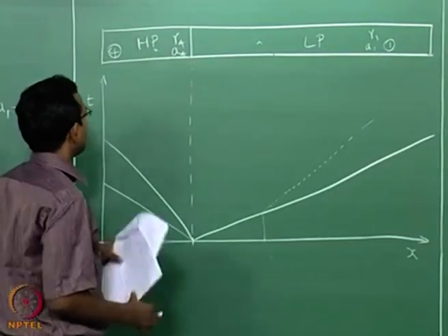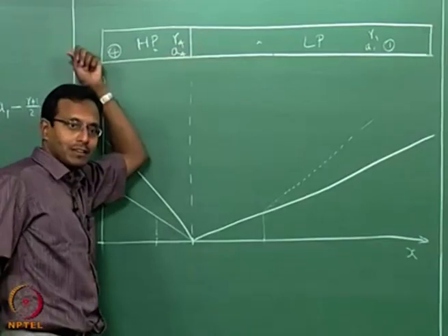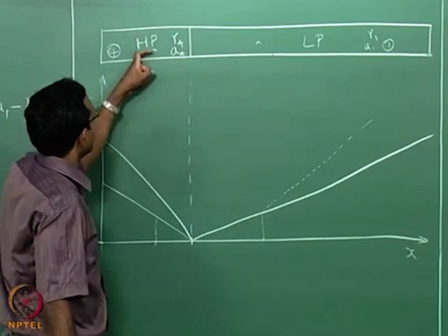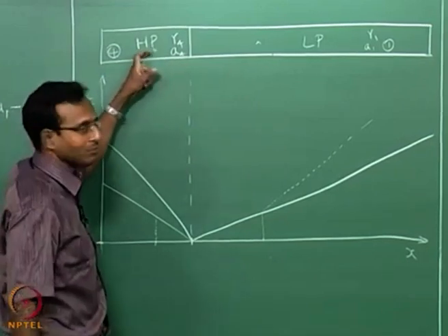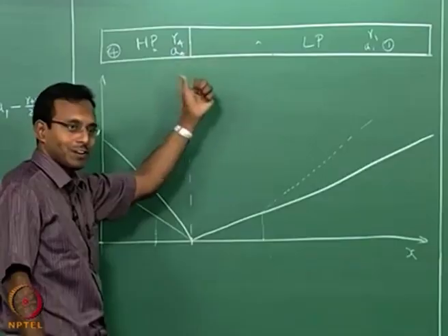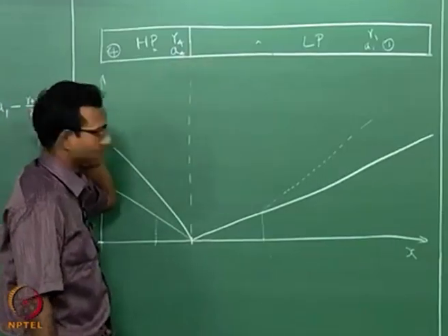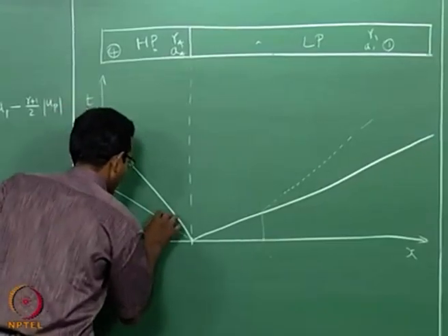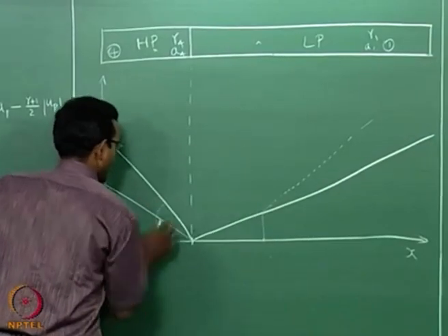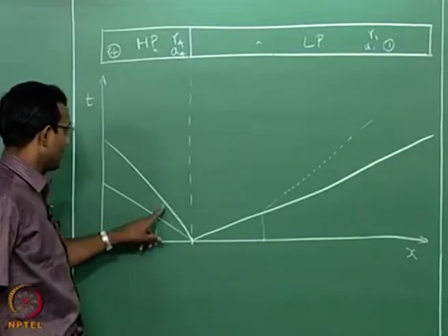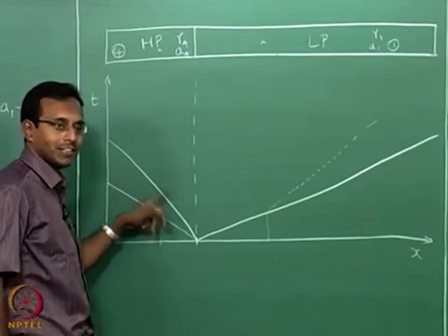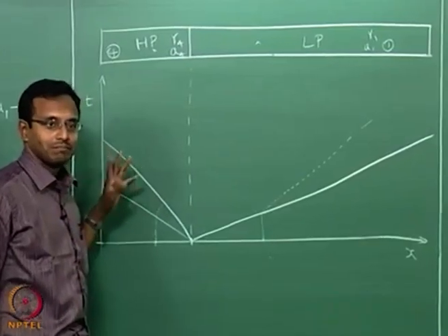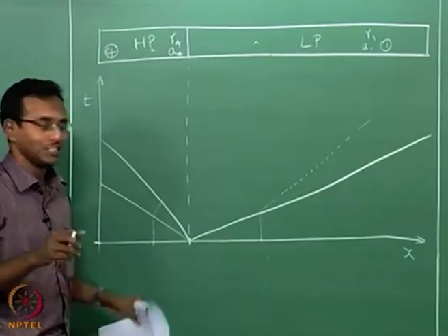After that, since it is an expansion wave coming this way, what will it do? It will induce a velocity in the opposite direction. So this fluid element at that point will want to travel the other way. Expansion fan will go this way to the left and the fluid element will want to go to the right. So it will start going to the right and it will keep on accelerating towards the right only up to the last expansion wave. After that things have come to equilibrium, it does not want to change anymore, okay.